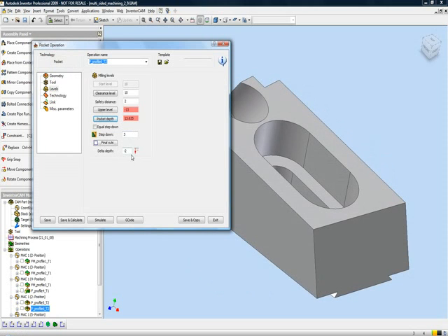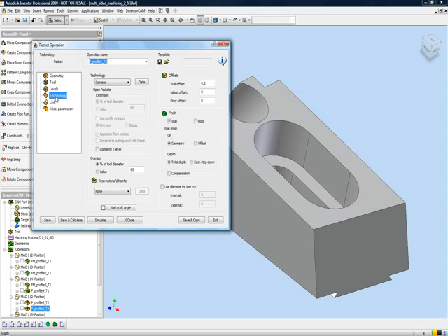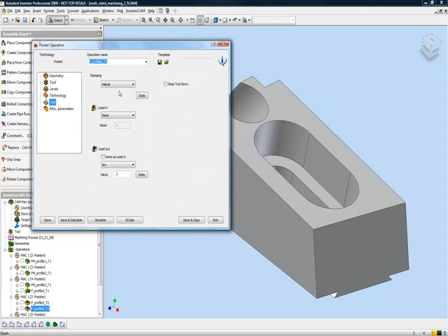Now I've added a delta depth of 2 millimeters to go a little past the area on the bottom to cut through the entire area without leaving a burr at the bottom. My technology will be, again, contour, the exact same things over here. And this time, since I'm not working on the floor, I do not need a floor offset, and my finish will be on the wall only. My link, again using a link of helical ramping and an arc lead out.